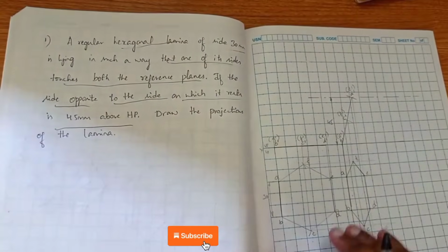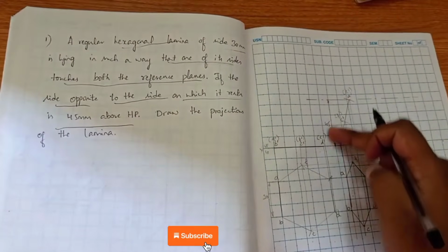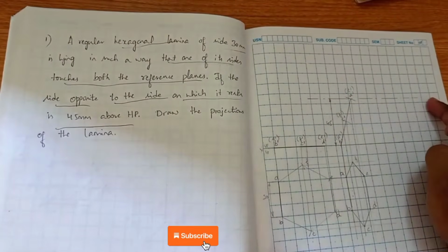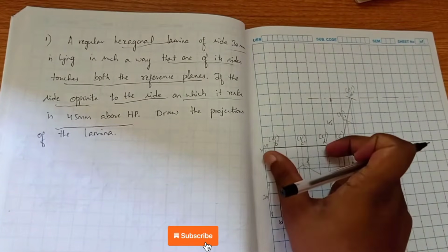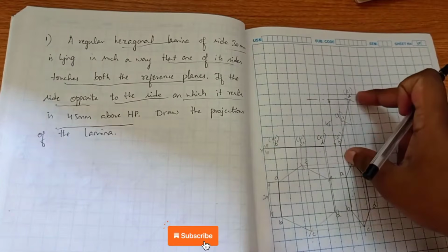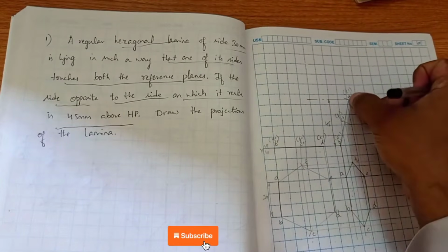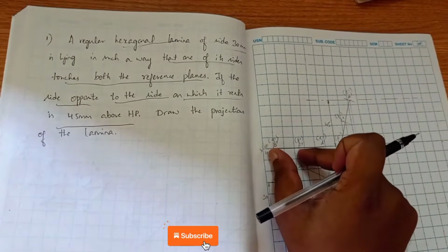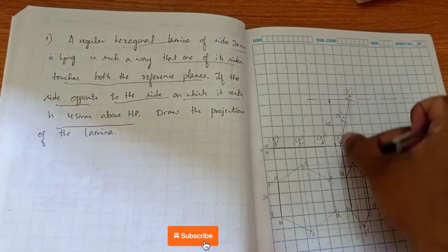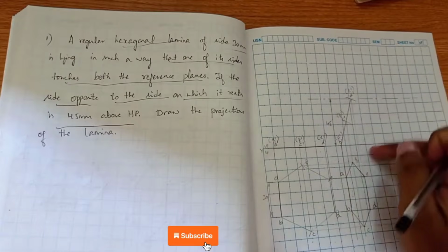So what we do after completing the first position, we draw a 45 mm line and draw the locus. Okay, after that I will be making a reference point. Then measuring the length from B dash D dash, I am cutting the arc. Then after cutting the arc I will be joining a line here. After that I will be measuring again from B dash to C dash and then cutting the arc on this line. So this is how we draw this second position.